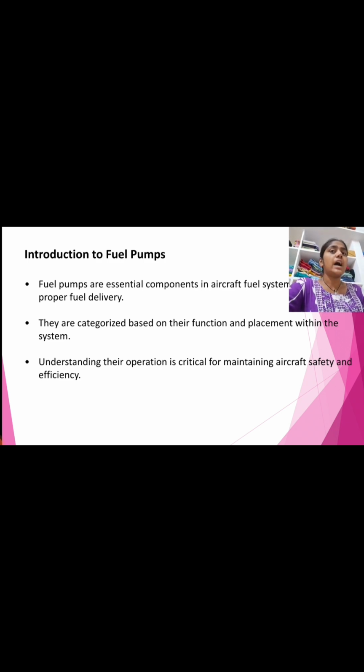Then next, coming to transfer pumps. Transfer pumps are used to move fuel between different tanks within the aircraft. In many aircraft, fuel is stored in multiple tanks to maintain balance and optimize weight distribution. Transfer pumps help in transferring fuel from auxiliary or reserve tanks to the main tank from which the engine draws fuel. This process is essential for maintaining the center of gravity within acceptable limits during flight.